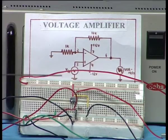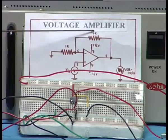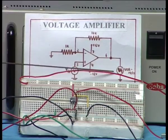If instead of 10K I had chosen 100K for the feedback resistor, then the gain will be 101 times. So by choice of resistors R1 and R2, if I make it 100K it will be 101 times, if I make it 50K then it will be 51 times the output.